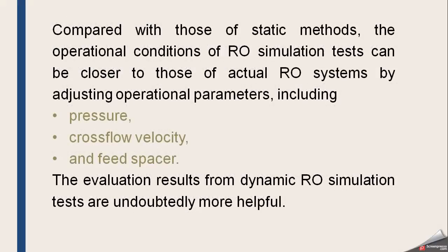So if we compare these two approaches, static and dynamic, the operational conditions of RO simulation tests can be closer to those of an actual RO system. Because it is a prototype system, we can adjust the pressure, cross flow velocity, and the feed spacer of the RO membrane, and also other parameters like temperature, concentration, and so on.